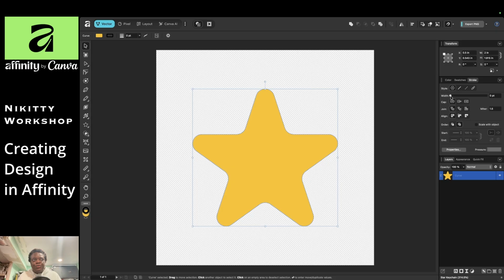I like to do all of this now so that I export it as an SVG. There's a way to add an offset within FreeCAD. I tried it before and it doesn't work consistently for me, so I'm not about to fight with the software to try to figure it out. So I'm putting all the outlines now in the SVG file, so when I carry over into FreeCAD, I just extrude. There are a few more steps to it, but basically you extrude to the thickness that you need and you're good to go. I'm not fighting with the machine to figure out offsets and Z. Like I said, real basic. I'm still learning it, so we're going to get there eventually.